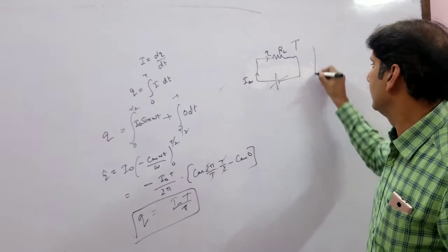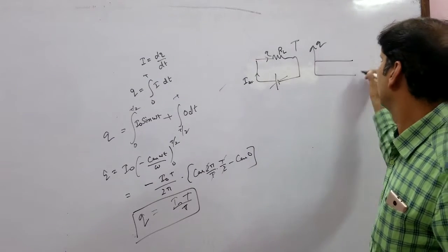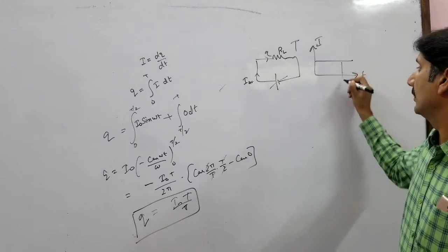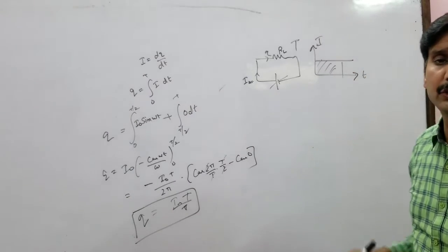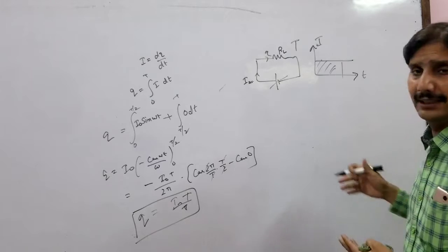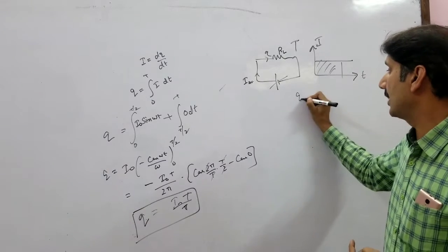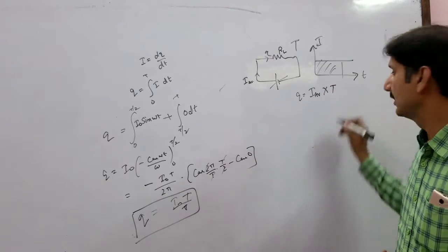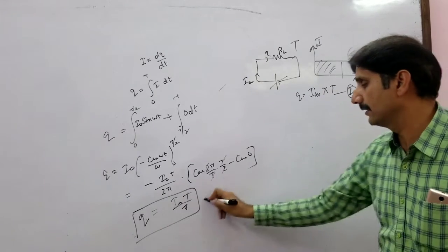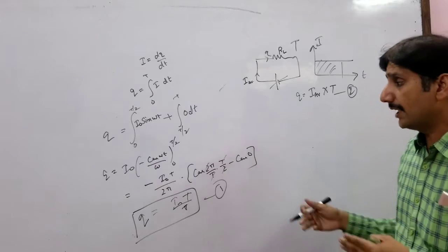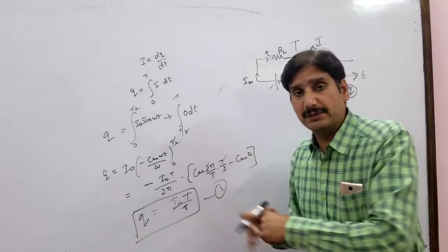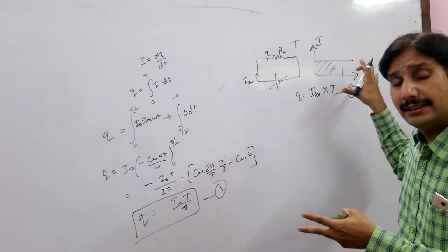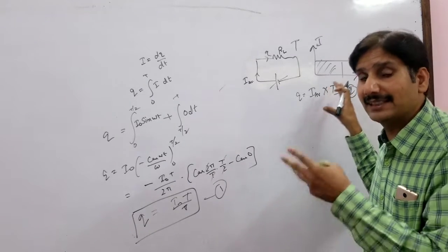So in this case, the DC supply is constant. Let's say current versus time. So it is easy to find out the total charge. You don't need integration. That's simply the area under the curve, which is current into time. So charge is basically I average into T. By definition of average value, the charge sent by that signal which we are considering should be the same as the charge sent by the direct current through that same resistance in the same time.